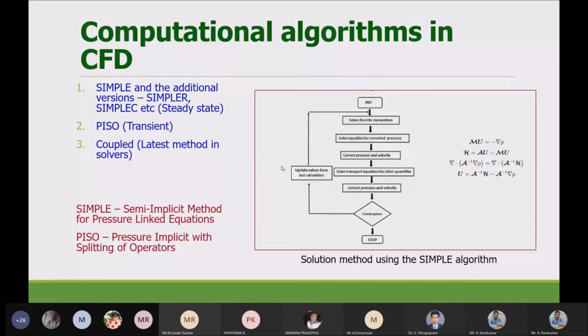So based on what the external conditions are, that is known as a boundary condition, and whatever heat you are giving, that is known as a source condition, and whatever object is being heated, that is our computational domain. So these are all the terms being used. Once it attains steady state, it's going to be constant. It's going to be a flat line. That's it. So if you're simulating that region, then that is a steady state simulation.